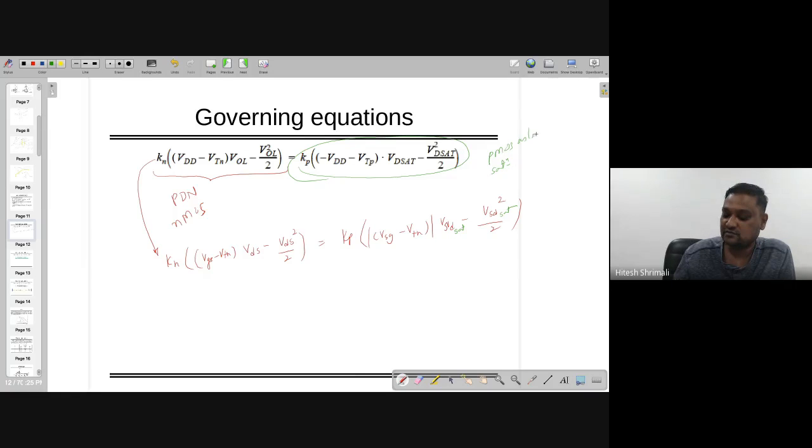So this is PMOS in saturation, PMOS as a load in saturation mode of operation, whereas this one is in linear. So, in the three conditions which we have already talked about, when A and B inputs are 0 0, 0 1, 1 0, we are expecting to have the output of 1 in the case of NOT. So then we have to make sure that this equation has to follow as written over here,